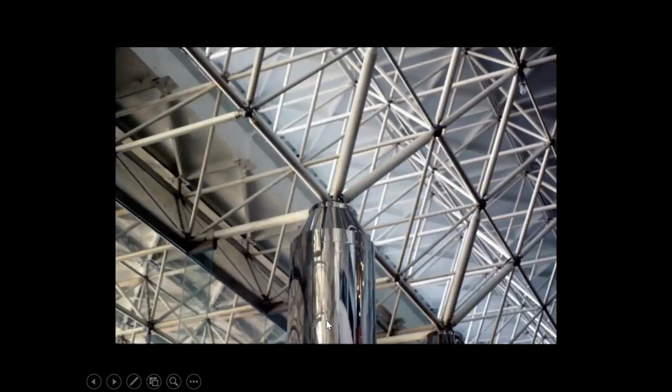Here's a close-up of a space frame. Here's the column, a joint, and then the various triangulated members, moving off and away from this joint. See the ball joints that enable many individual members to join at one point. And it's these joints that make space frames quite expensive. And you probably don't see many in Indonesia. There'll be a few, perhaps in the canopies of your 5-star hotels.